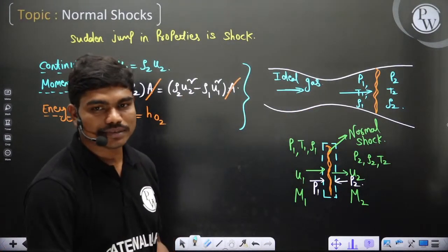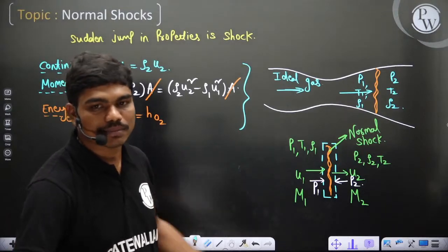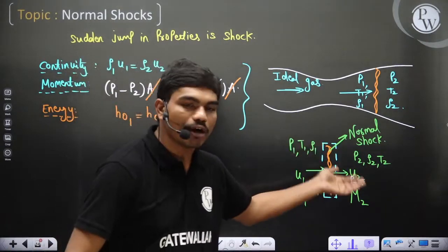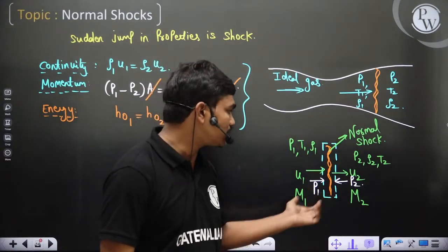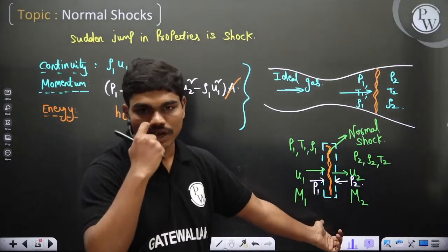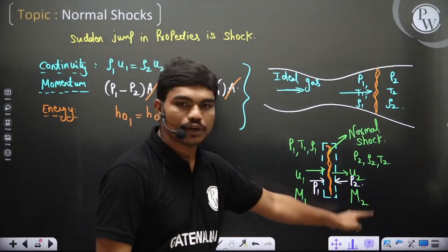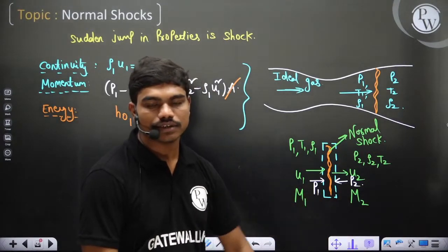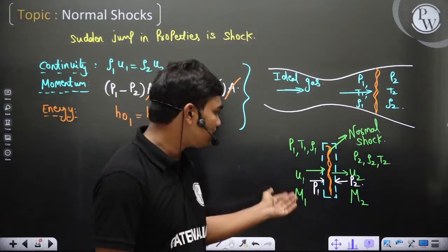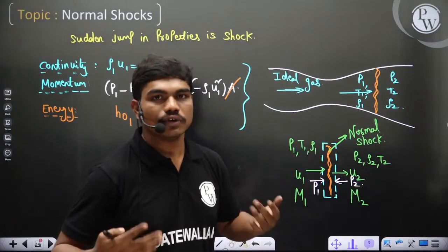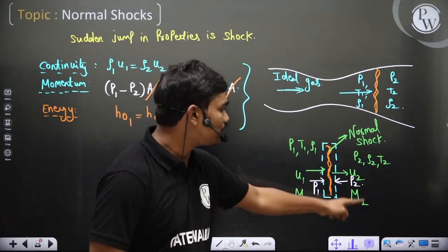No Mach number relations, because you don't have any Mach number relation. You have to generate that. You have to find out what is the relation between these Mach numbers. That's how you can identify. If this is known, then you can calculate this, correct? You actually have to derive some relation between these 2 Mach numbers. That's how you will come to know, if this is the Mach number here, then what is the Mach number here.